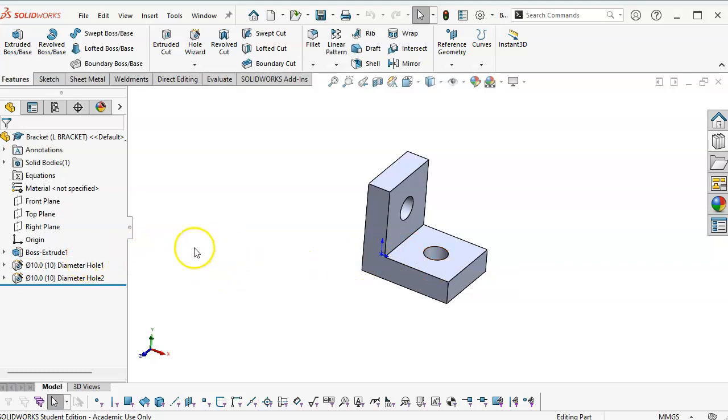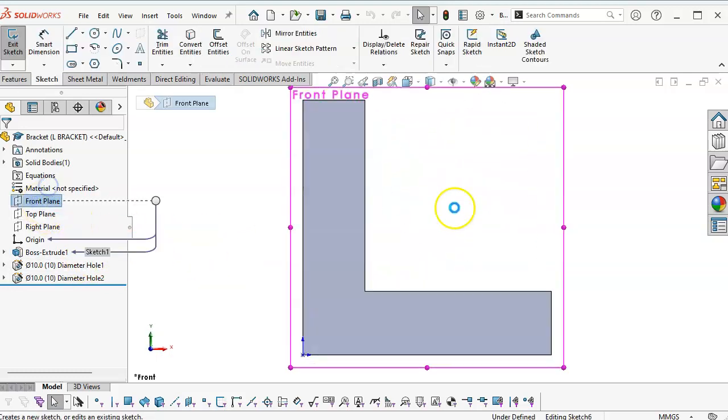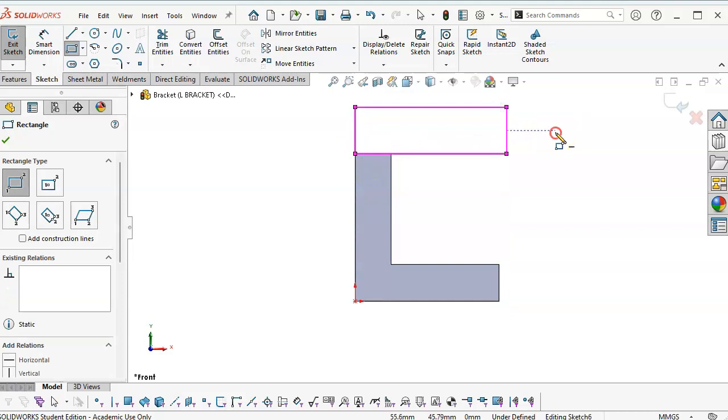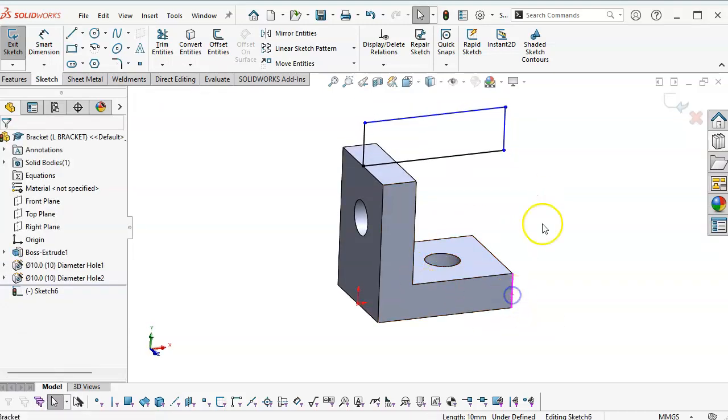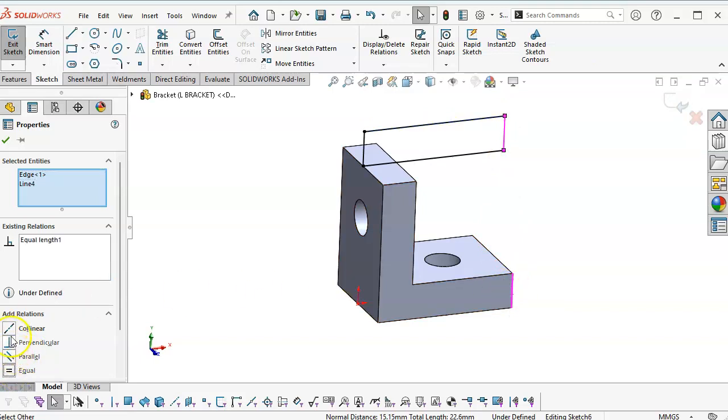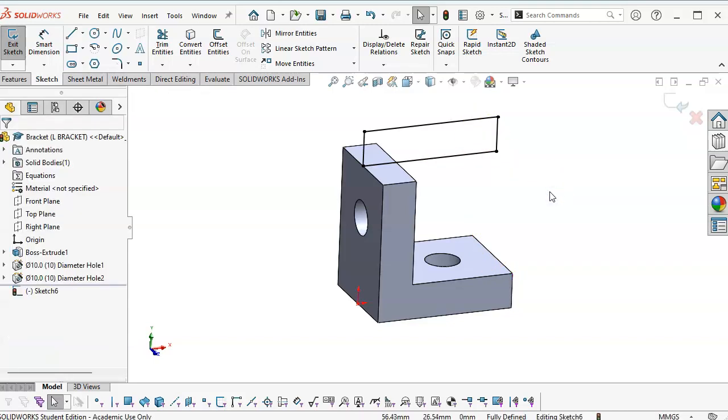And we're going to add this now separately. So on the front plane, I'm going to open up a sketch and we'll find coincident to that corner. I have a thickness, but I don't know that I can make those equal between the features. Oh, well, if I can, I'm going to. So selecting the feature, selecting the edge, telling it that it is equal, and then also collinear. Even though this edge exists forward of the front plane, because we did mid-plane, I'm projecting back into that plane and saying I can do this sketch without any dimensions in it.